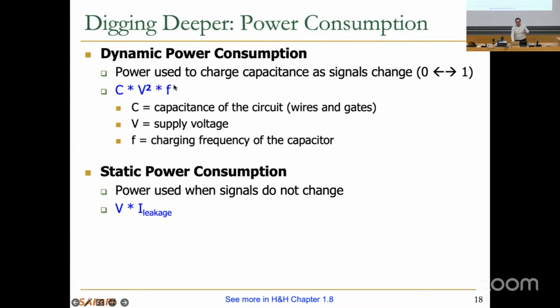So the overall power that you consume is a function of dynamic power, how often you switch. If you're never switching, something is leaking. For example, my cell phone in my pocket, I'm not doing anything. Hopefully it's not doing anything also. But if it's turned on, it's leaking. So the battery will leak over time because the circuit is actually draining static power consumption, essentially.